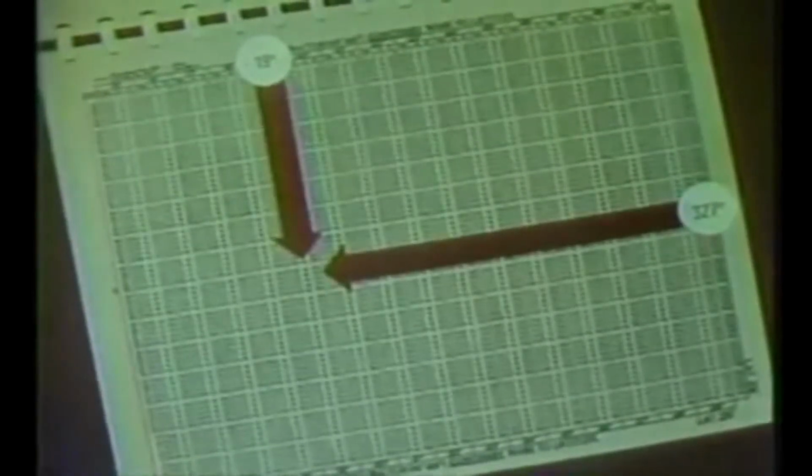Move across the tables to the column for the whole degree of declination of the Sun, 19 degrees, and you read HC for 19 degrees as 33 degrees 11 minutes. A D, or correction factor of minus 49, which we'll discuss in a moment, and an azimuth angle, Z, of 142 degrees. The D value is the total difference, or change, in minutes of altitude between the declination of 19 degrees and the declination of 20 degrees.